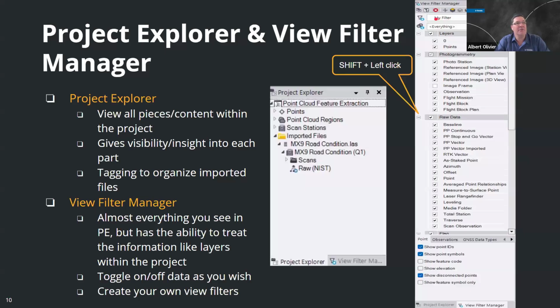In here, you see my filter. There are options to actually set up different kinds of view filters, and that helps especially when you want to hide and quickly unhide certain layers and elements in TBC. Setting up a view filter that shows you what you need is a quick way to cycle through different views in TBC.